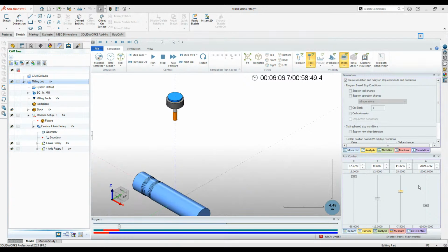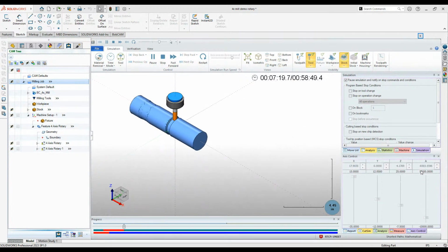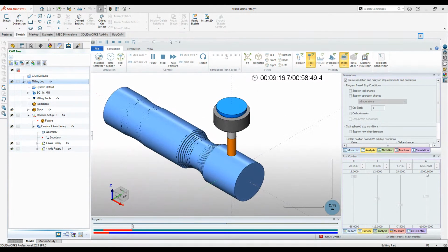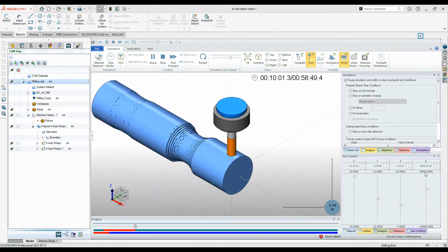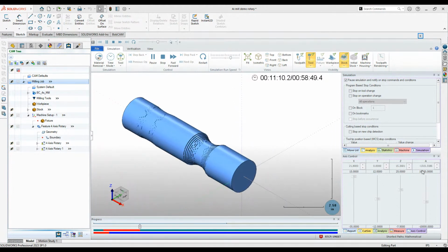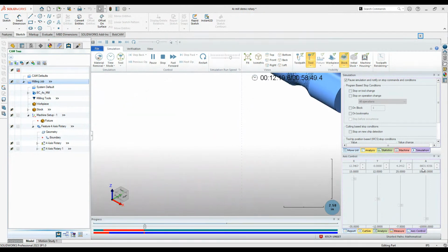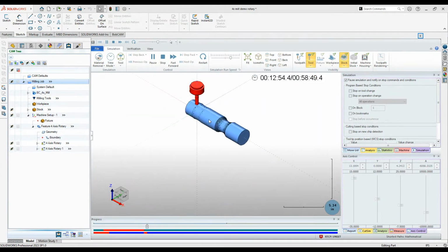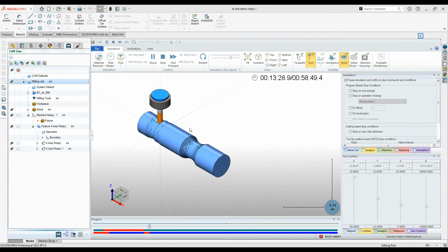It'll rewind the stock back to negative 10,000 and then start doing the positive direction of rotation again, so that you don't have to rewind it yourself. You can just have the tool retract, rewind, and then go back down once the stock has rewound around the rotation axis there for your rotary table.